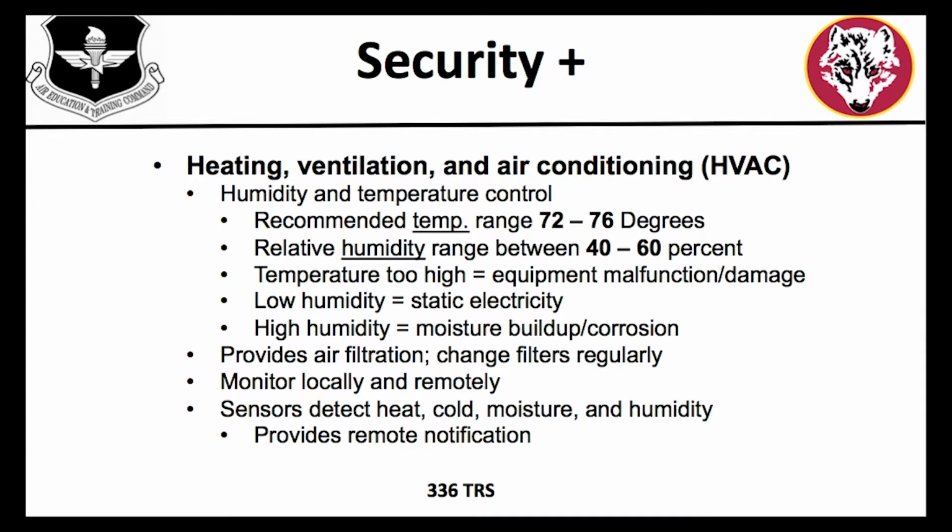Once again, if your temps are too high, your equipment's going to start malfunctioning, shutting down. That's not a good scenario. In the environment where all your systems are housed, if the humidity is too low, let's say below that 40 percent, you're going to have static electricity, ESD. Too high, then you're going to have sweating of those devices internally, where you're going to have corrosion and short circuits inside. So obviously we probably think about that for HVAC, but don't forget that the HVAC system is also there to filter the air. These tiny particles of dust can, over time, degrade the performance of your devices.